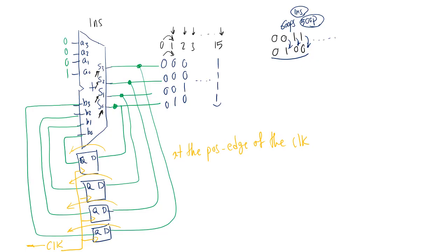The lesson that we learned from this example is that, it's not the best counter, by the way. I could make a counter using only these 4 flip-flops. I didn't really need the adder. If somebody really loves to use adders, this is the way to go, but you're wasting a lot of resources.